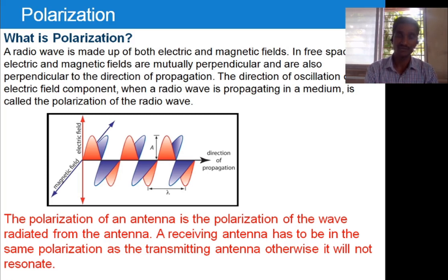If you transmit electromagnetic waves from one point to another point, at the other point there is a second antenna that works as a receiver. If at the transmission side you use vertical polarization, and at the receiving side you use an antenna with horizontal polarization, then the transmission is not performed in a good way. For proper transmission of the signal from the transmitter to the receiver, both the transmitting antenna and the receiving antenna must have the same polarization, vertical to vertical.